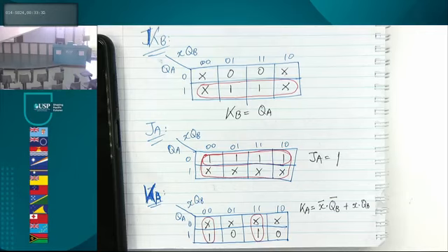Okay? So from there, we draw the state diagram. First we will draw the state diagram in normal decimal numbers, 2, 4, 6, 8, 10. If x equals 0, if x equals 1, it goes the other direction, right? From the state diagram, we go to the state table, right? From the state table, we extract the formulas for the flip-flop inputs, the algebraic equations. From there, we draw the circuit. Well, if you have got the hardware option, then from drawing the circuit diagram on paper, you implement on hardware. Okay, so that's the process.